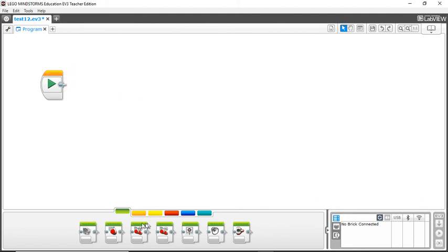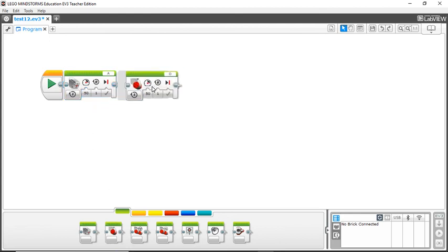That's mainly all, actually, let me touch on this. This is a medium motor. If you have a medium motor attached to your robot for attachments or whatever you have it attached for, this is the block you want to use. You don't want to use this one. This is a large motor block. You want to go medium motor if you have the medium motor. So then again, just check your port, etc. Plug in your speed, 0.5, and then type in your rotation, 0.2.